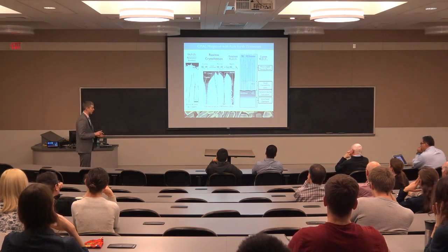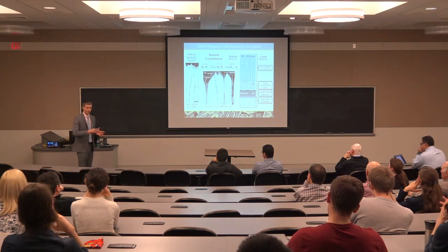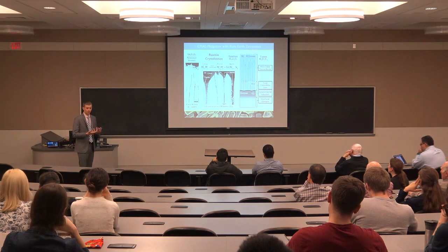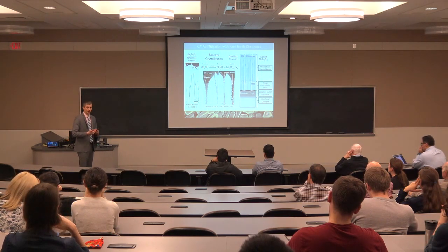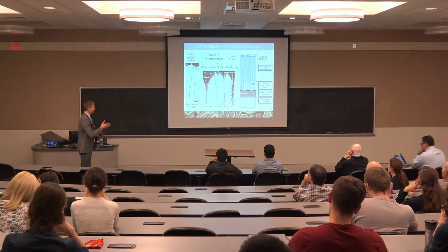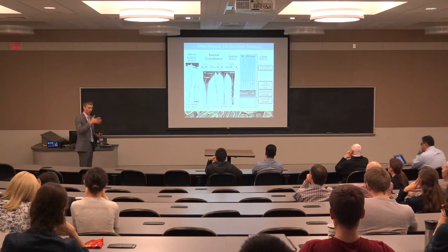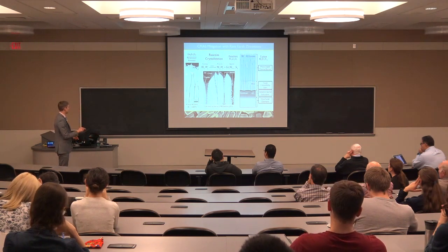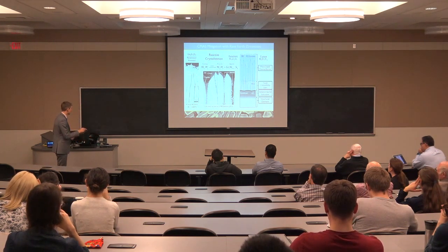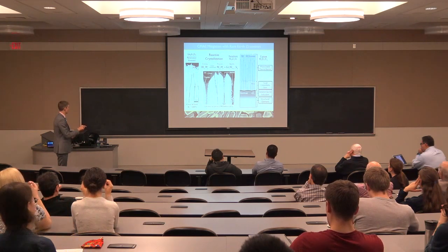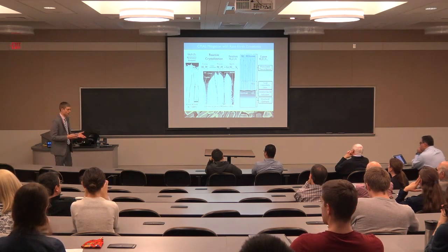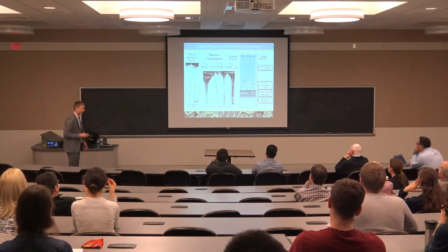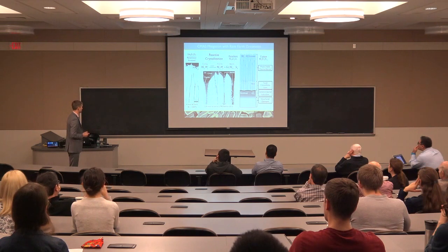And so this interaction, within a matter of seconds after the dissolution happens, we get apatite precipitation, and with the growth morphology, this sort of faceted needle-like morphology, it very quickly fills the gaps in the coating microstructure where the melt is penetrating, and the penetration stops. And so, in this case, this is something that you can see in 4 hours at temperature, and the penetration is just a few tens of microns instead of hundreds of microns that we would expect in a typical coating. So, again, apatite is the key to this process, the fast nucleation, the fast growth.